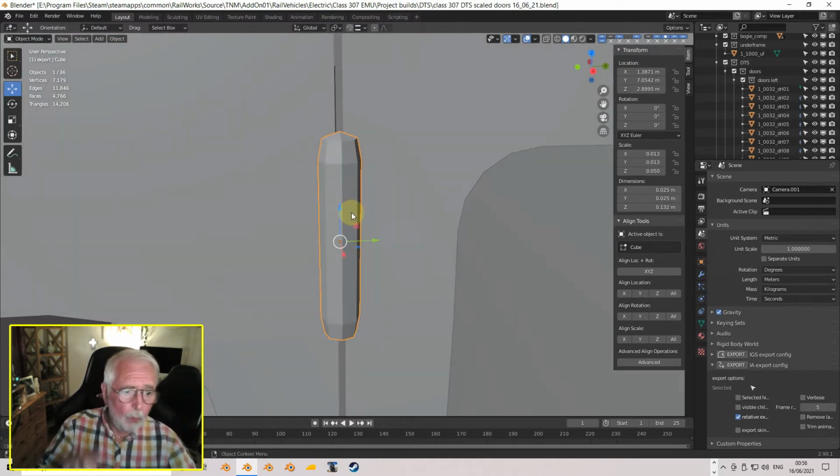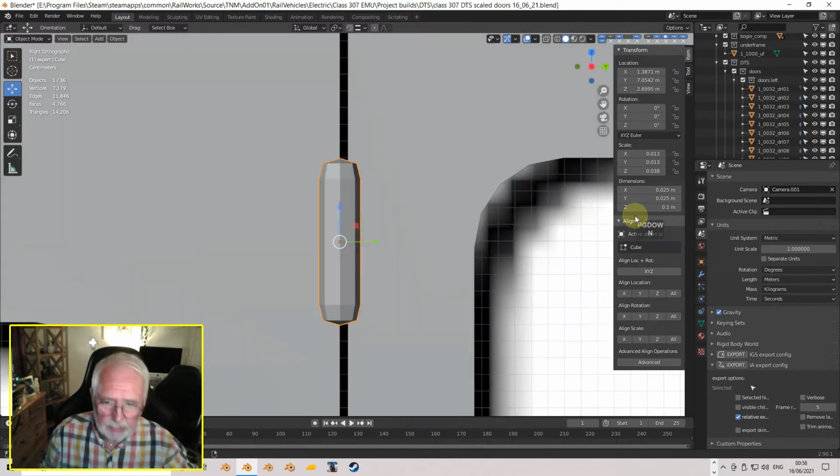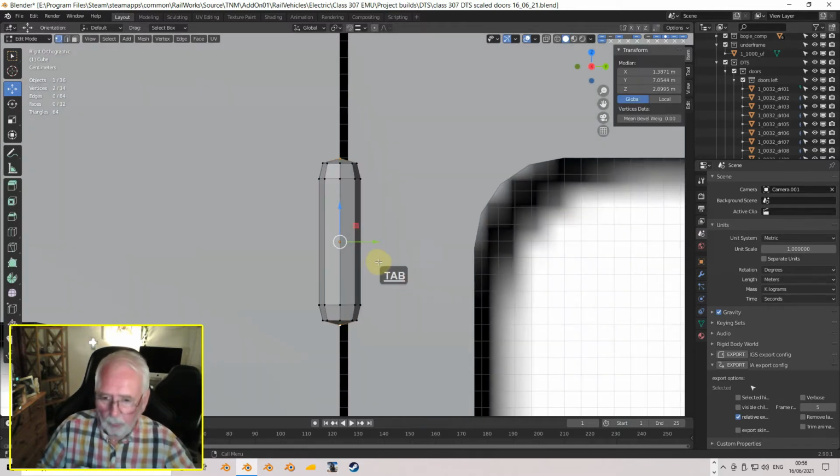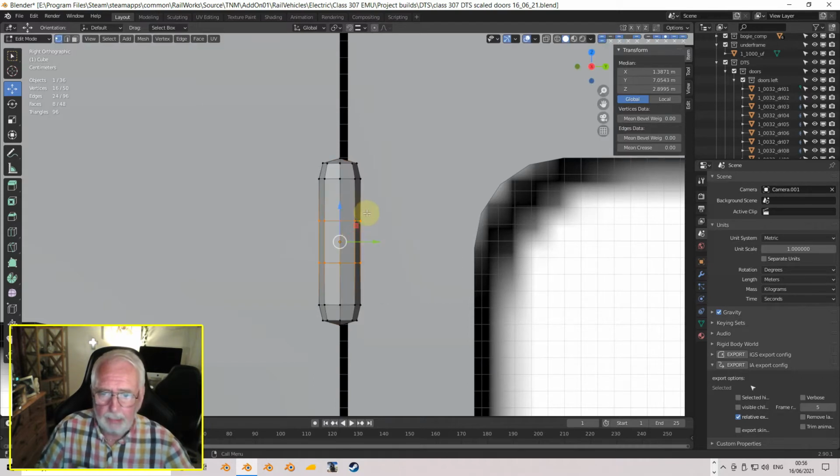Right, okay, what I want to do now is reset the height, so I've extended it there with that. So let's change that back to 10 centimeters. Okay, and side on. Now what I want to do is make a cut in the center, so we've got two halves of a hinge. So loop cut. Okay, two of them there. Now I'm going to scale them down.